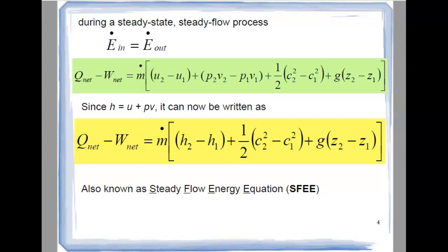So in this open system, we are going to learn how we are going to make use of first law equations, and then it becomes the steady flow energy equation, and how we are going to apply it in the open system devices. So you can see here the term U, internal energy, and this work boundary is deduced into H is equal to U plus PV.